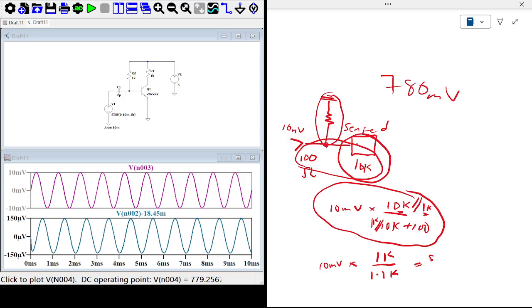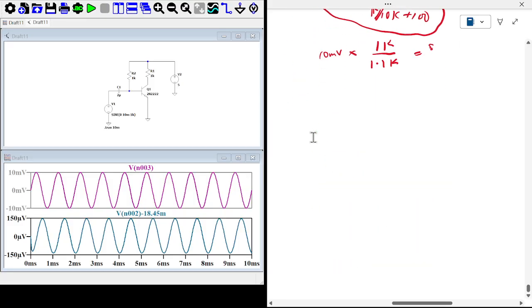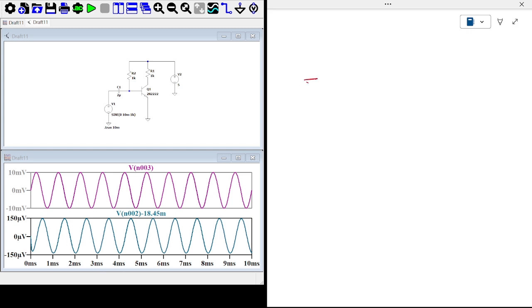So my amplifier failed. What I want to do is start from a point. Assuming I know my VCC is 5 volts and I want the headroom, if you've not watched the video on the headroom, you can do so. I want the headroom to be big enough, so I want the bias output voltage to be resting around 2.5.